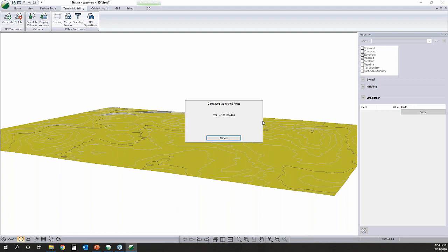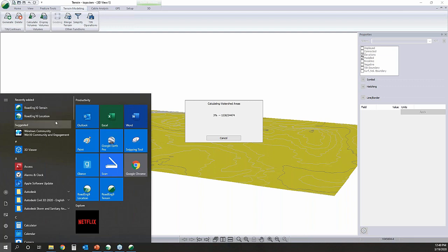The next one here, Matt: we do P-line surveys. Can I combine those with our LiDAR? Yep. Actually, I don't think I have anything prepared for it, but yes, you can. If you have a LiDAR data set and you want to combine your P-line with it, you can do it a bunch of different ways, but the easiest one is to just use your P-line as a reference. You can get your offsets from that.